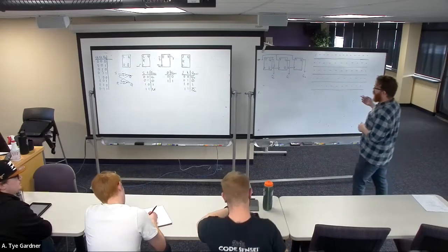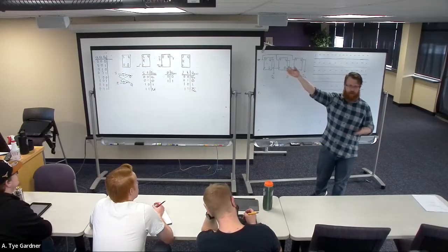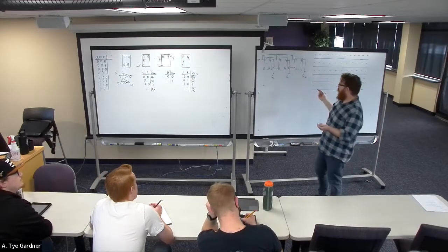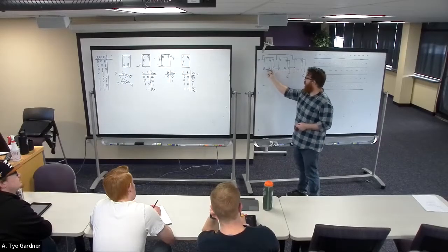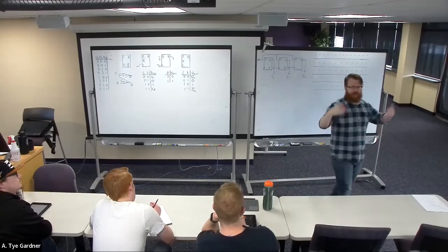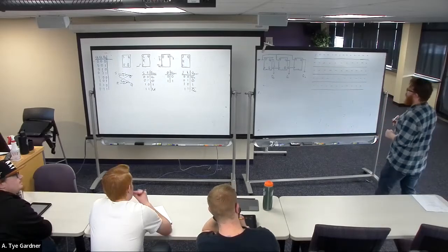And so we're going to say that all of my Q0 to Q2 start at zeros. We're going to assume that we have a reset signal, right? It's not unreasonable to assume that there's a reset signal on each of these. You can build it really easily. You reset it, it goes to 0. We turn on the enable, it starts counting.